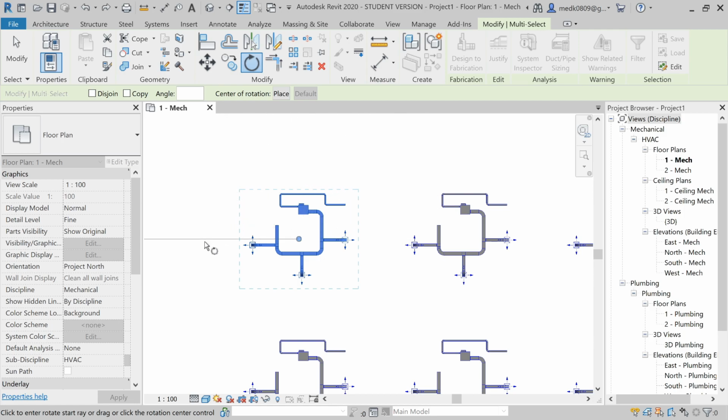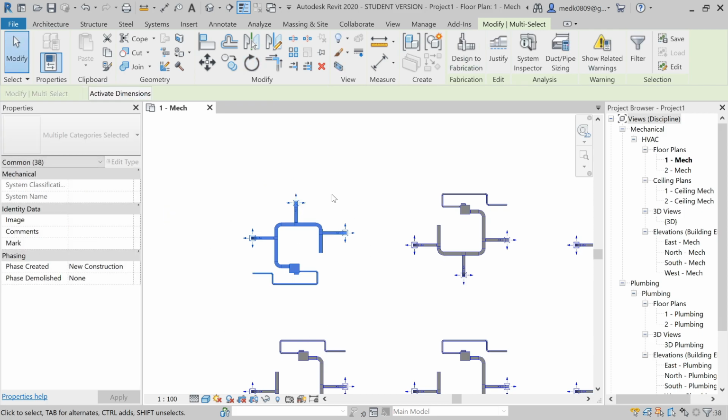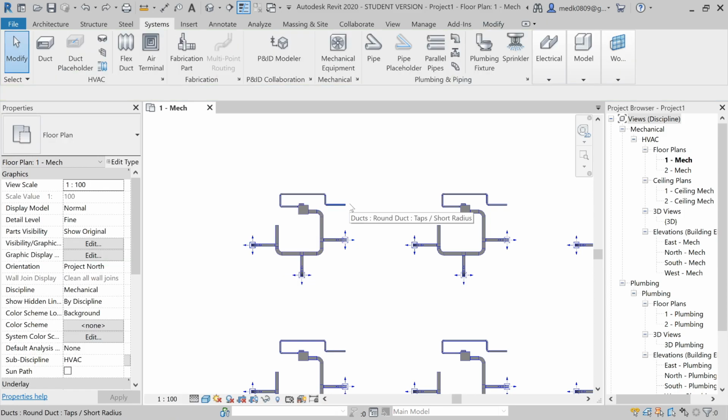I place this stick about the x-axis, okay, for the reference, or you can say it is the baseline from which you will define the angle. Okay, so I will click over here, and then you can specify the angle about which you want to rotate the circuit. Let us say I will select 180 degrees. So just enter 180 degrees from your keyboard and then press the enter key, and your circuit will be rotated by an angle of 180. Let's make it Ctrl Z. Okay, just pressing Ctrl plus Z, you can undo this.